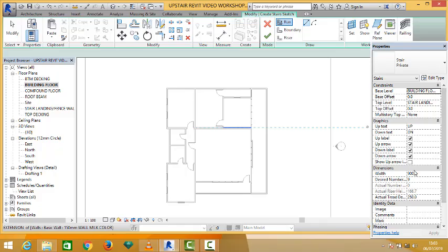And then of course the stair width can also be changed. Okay, 900 is what we want. And then the desired stair number can also be changed. Now the software does something here. If this desired stair number is not okay, the software will automatically alert you and give you a desired stair number. And then this is the actual tread width, which is 250.